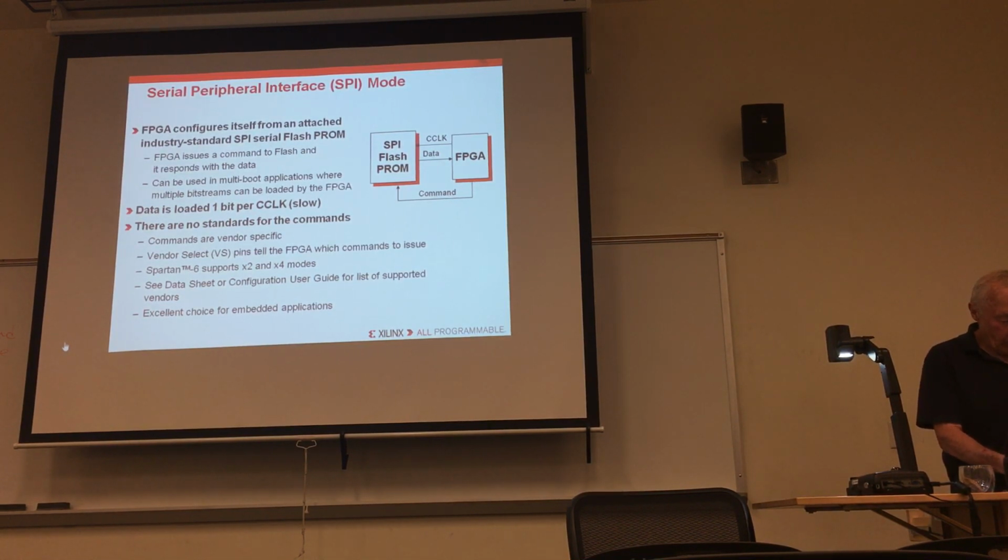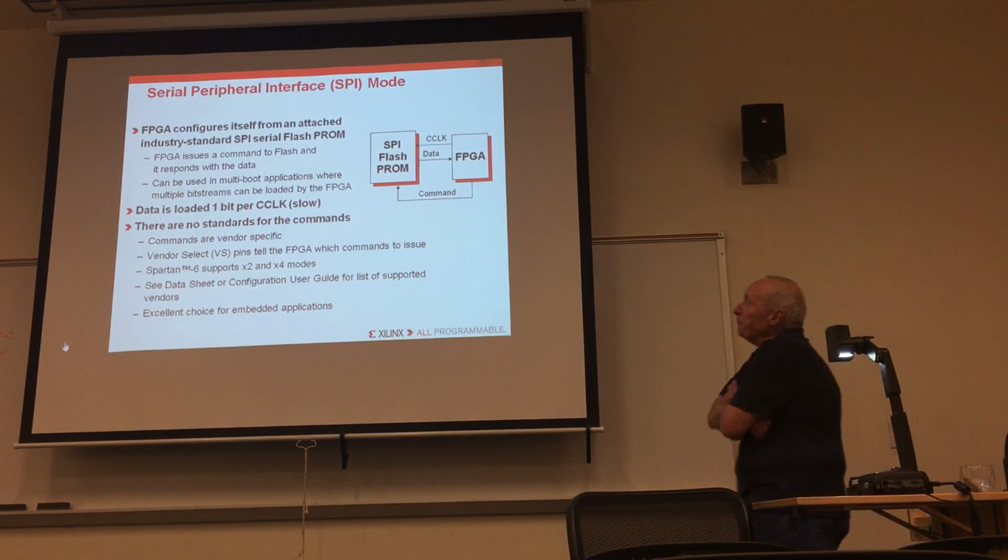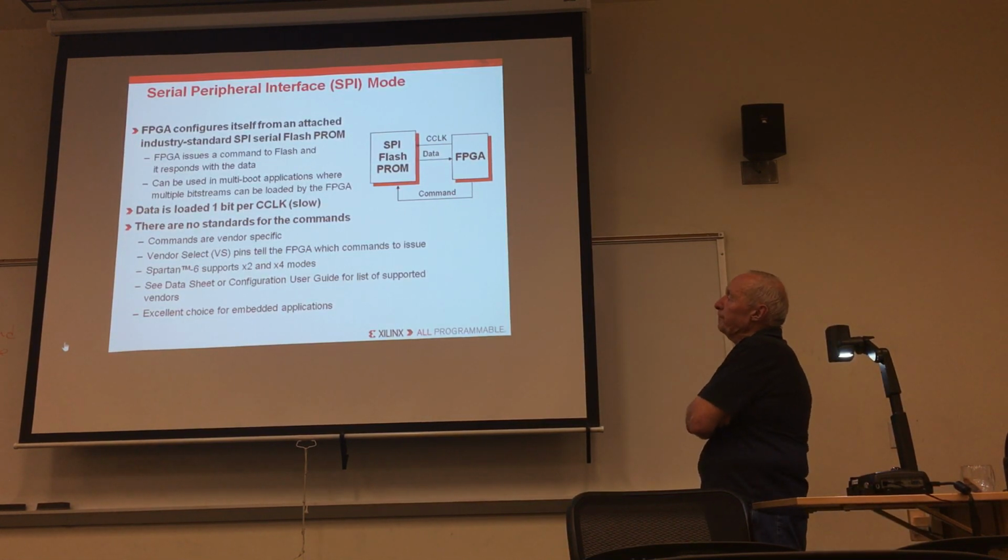Likewise, this is a popular configuration for designers that want to load a single FPGA with different bit streams at different times while their application is still running. This reconfiguration is referred to as multi-boot applications and should be planned sufficiently so you can choose a SPI flash PROM that is large enough to accommodate all the additional necessary bit streams. If you're building an embedded application, it is also possible to store your software code in the flash PROM as well. So likewise, plan on choosing a sufficiently large PROM to store your software.